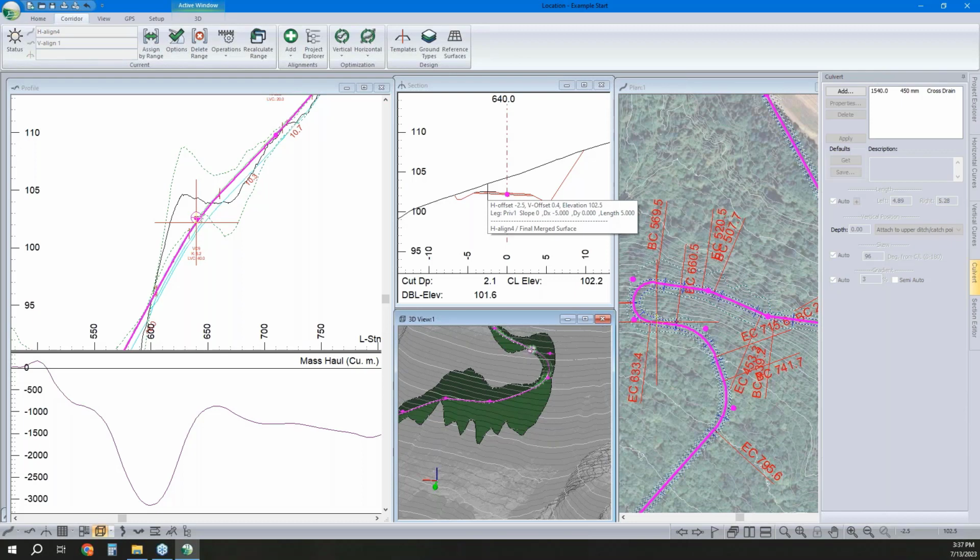And just by adjusting the cross-section template geometry, we've added things like surfacing, the crown, ditches. Then we took that a little further and we had an independent ditch. So the ditch is following our road as in attached to the prism, but the grade is at a different slope than the road grade.